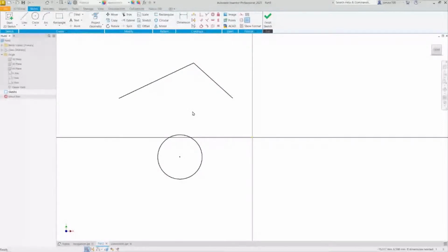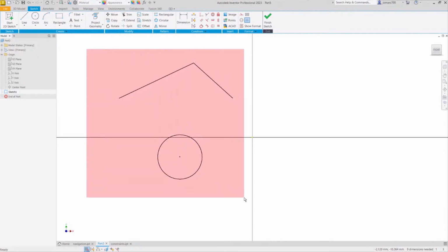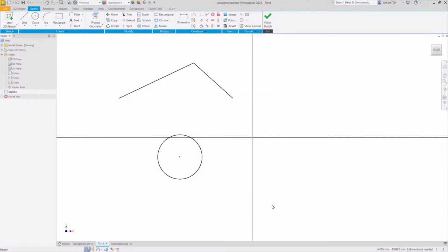Having a clean slate, I'm going to place my cursor here, left click and hold. And now I am creating a window selection. So recall in AutoCAD, or from here at this location, bottom right, left click and hold. Notice the difference. This is now a window crossing selection, same in AutoCAD. Release. With all of this entity selected, I'm simply going to hit delete.